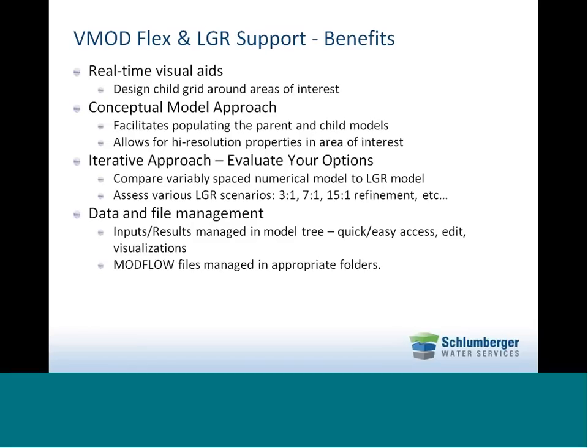You design the geological structure, and design your rivers or your well locations with shape files or other GIS data, and then the translation and the cell assignments are done for you automatically. This also allows you to have high resolution properties in your area of interest.